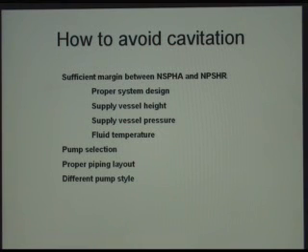And then next time you pull it in, you have to accelerate it back up again. So if you drop below the vapor pressure locally when you're trying to accelerate the fluid inside the pipe, you could have vapor forming at that location. But as soon as that piston stops, that's going to collapse and become a vaporless liquid again. And that'll happen in all different places. So if there's any kind of pitting, it'll be spread out over a huge area. So it's not localized like this is, and you don't have the same potential for mechanical failure like you do in a pump impeller.